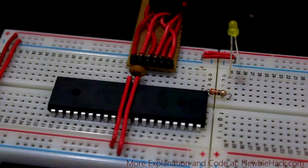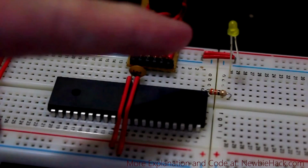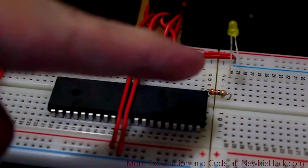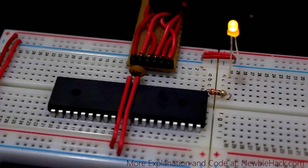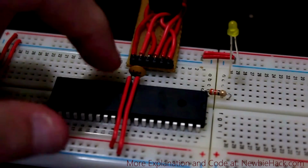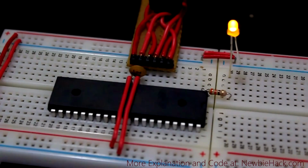Okay, we can see that it is blinking. It's on for a second, off for a second, on for a second. So it looks like it's working correctly. So let's go ahead and burn the fuses and see if we can get this thing to go faster, because with installing the crystal, this should blink 18 times faster.